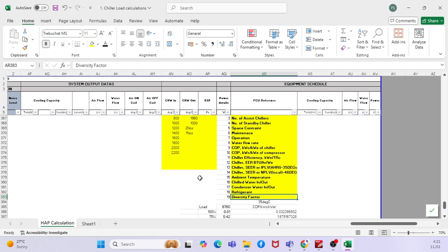That is a profile. Actually speaking, when you talk about diversity, it is nothing but your profile basically. So that will give you the smallest chiller when you do the selections. After you apply the proper profile, you may not require to apply diversity because you already applied diversity in the profile. When the lighting will be operated, how the humans will be during that time to time, and what the equipment load will be during that time to time, everything is based on that, right?